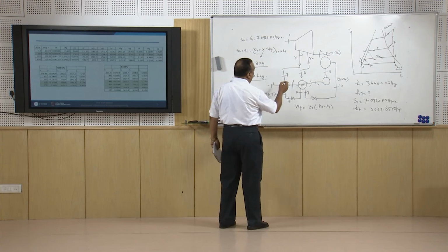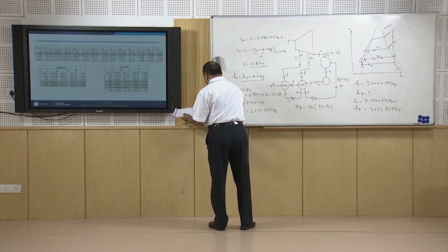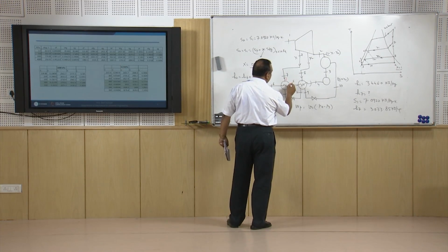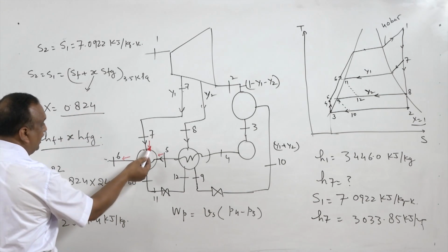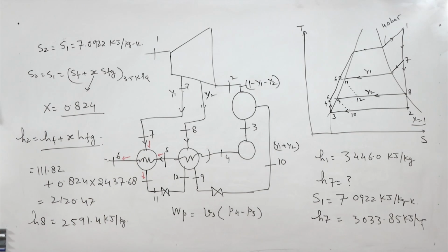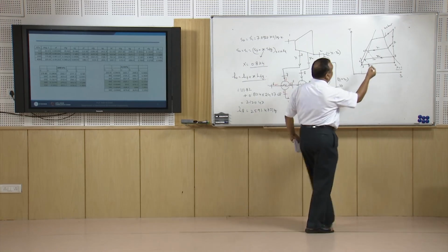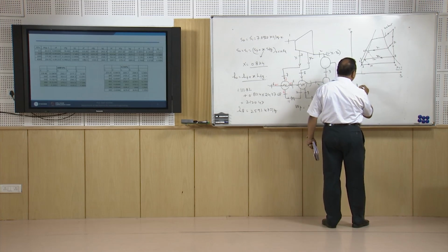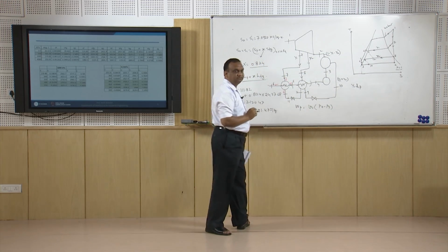Heat balance means how much heat is coming to the heater, and how much is leaving the heater, or the enthalpy of the fluid leaving the heater and the enthalpy of the fluid coming to the heater. Now, we will do the energy balance: the energy of the fluid available here is Y1 H7. Y1 H7 is the energy coming from here, right.